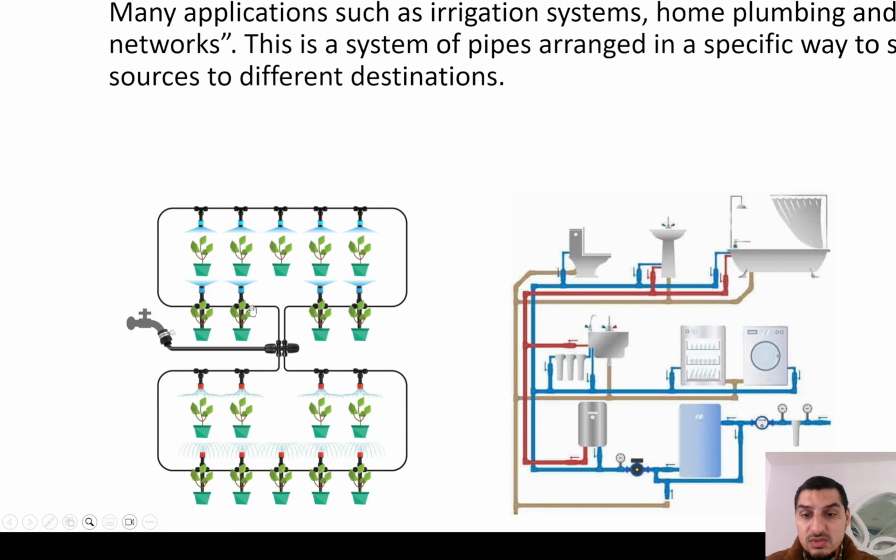So if we apply these similarities between these two cases, you would see here that a pipe that's branched into two branches is equal to two resistances in parallel. So the volumetric flow rate 1 plus volumetric flow rate 2 is the total volumetric flow rate. So this node is splitting the flow to two different branches with different flow rates, and again the flow rates depend on the losses, which is the same as the resistances here. So V1 plus V2 is the total volumetric flow rate, but the pressure difference is equal.